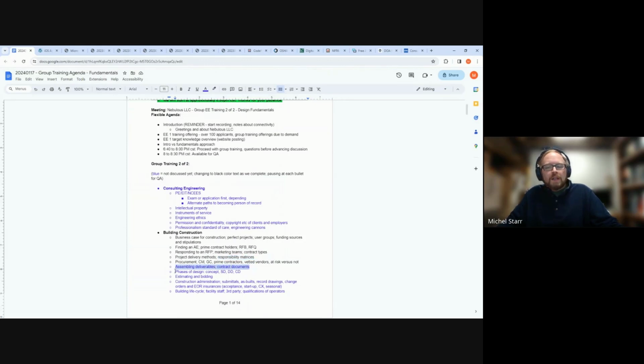So the consultants then assemble deliverables, the contract documents, and to do that they have to go through phases of the design. A usual sequence could be a conceptual plan, a schematic design, design progress, and then construction documents to then be estimated by contractors and bid. It doesn't mean that they will be exactly in that order for every project.